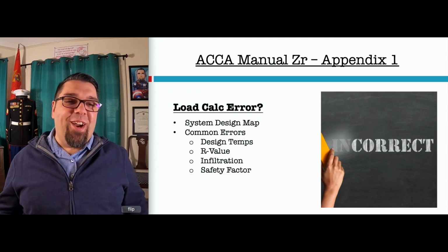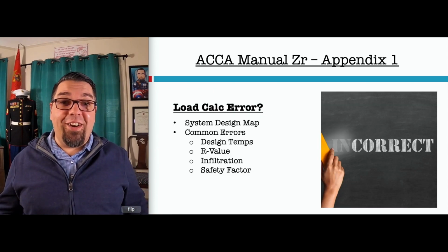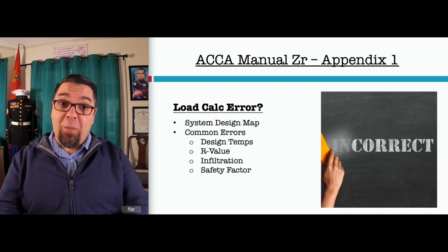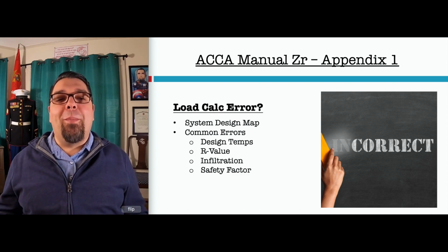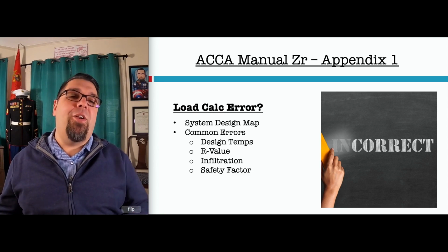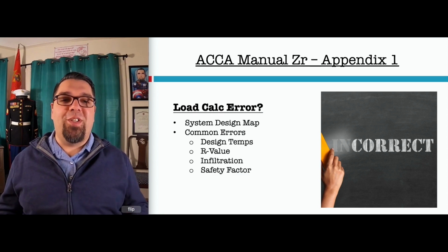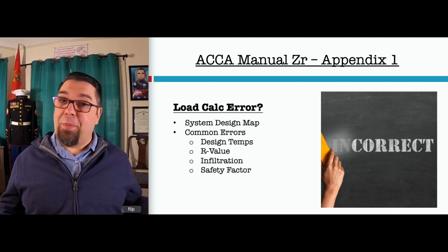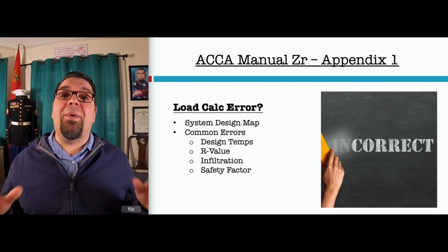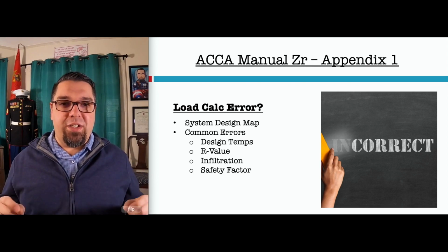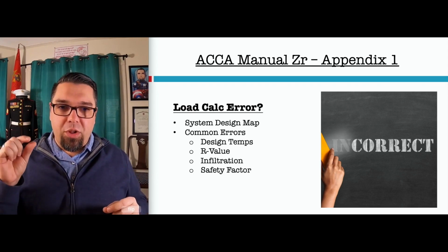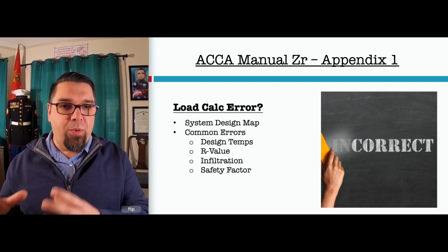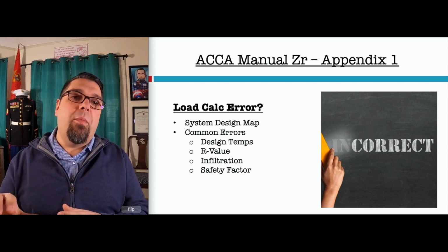I always laugh when I hear about this, all right? Load calc errors. I know nobody watching this makes errors on their load calcs, right? So, and everybody does load calcs, but you gotta remember, when I say a load calc error, it's not an obvious error. You guys hopefully know the difference between a vinyl framed window and a wood framed window, single pane or double pane. Hopefully you guys understand the basics there, all right? What I want you guys to understand, if you make an error on the load calculation, this is the system design map. This is your map before you enter the woods, right? If you've heard some of my in-person talks.